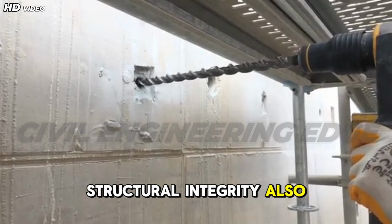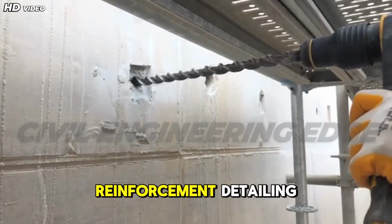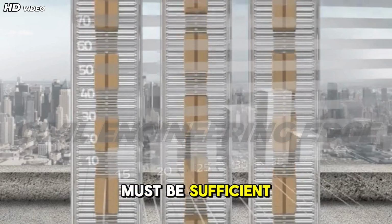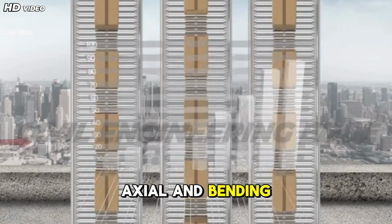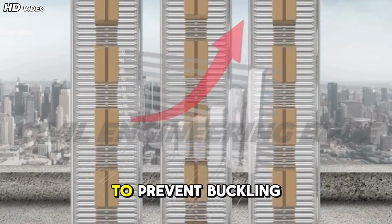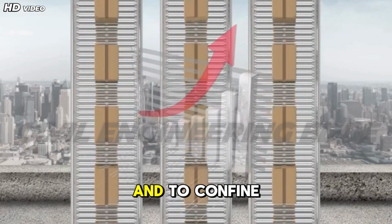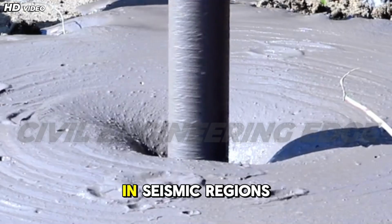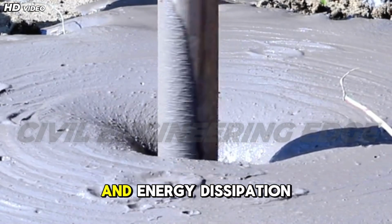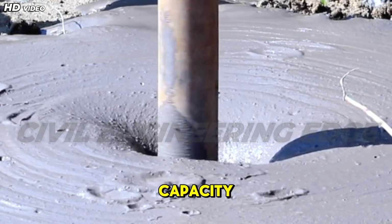Structural integrity also depends heavily on proper reinforcement detailing. Longitudinal reinforcement must be sufficient to carry axial and bending stresses, while lateral ties or spirals are necessary to prevent buckling of main bars and to confine concrete. In seismic regions, closely spaced ties improve ductility and energy dissipation capacity.